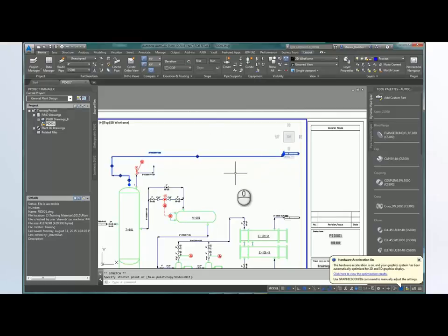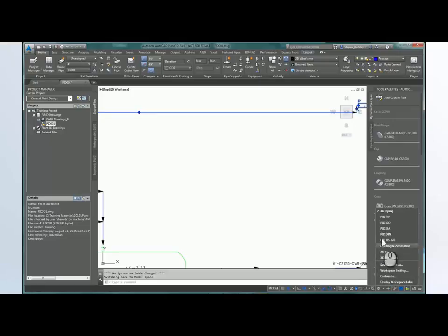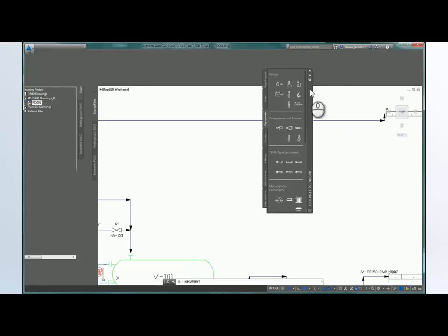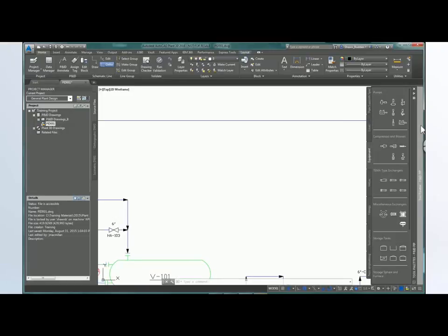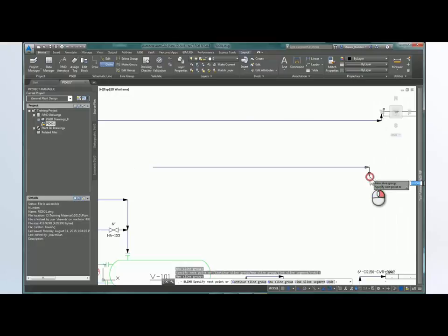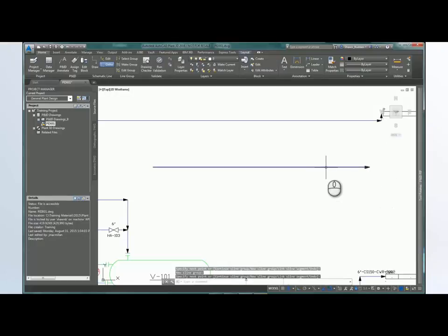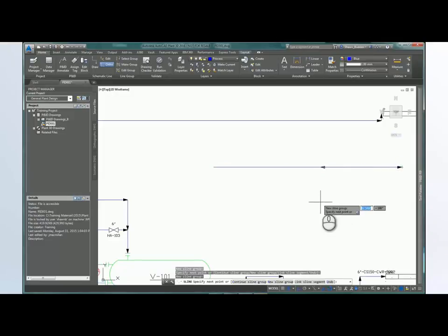Now, if you had a line that you wanted to stretch, let's go ahead and get us a little clean space right here, and we'll change our workspaces so we can get some P&ID lines. There we go. Anchor that in there and pick us a line. All right. If you need to stretch a line, you'll see these pluses, or if you want to shorten a line. It's very simple to use those as well.